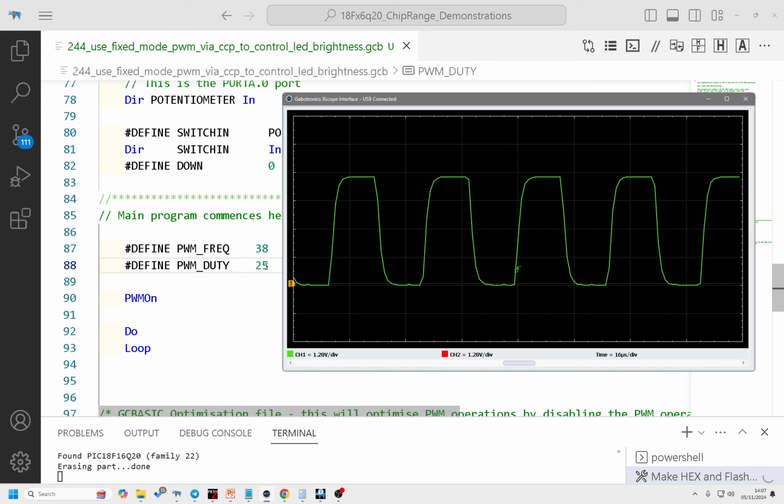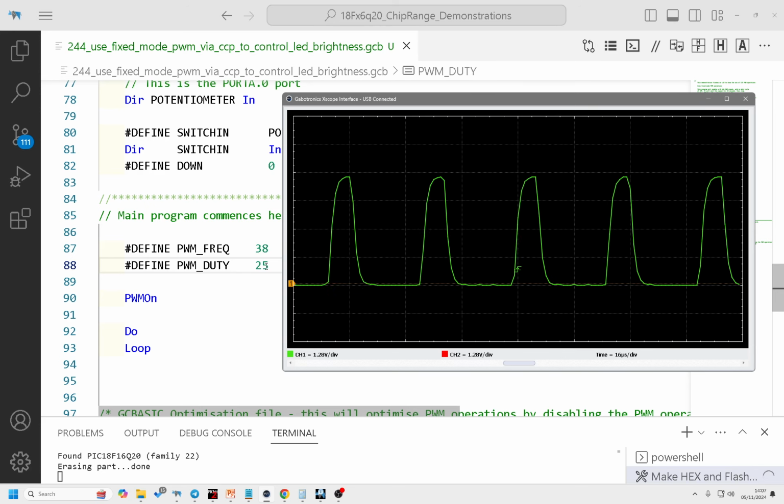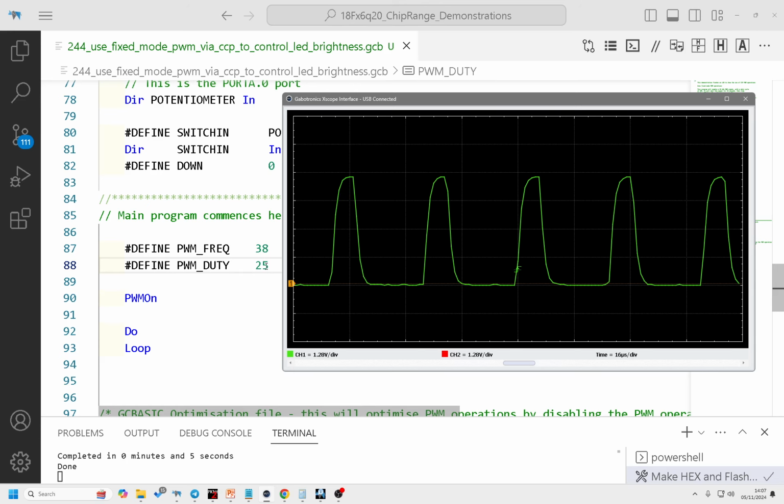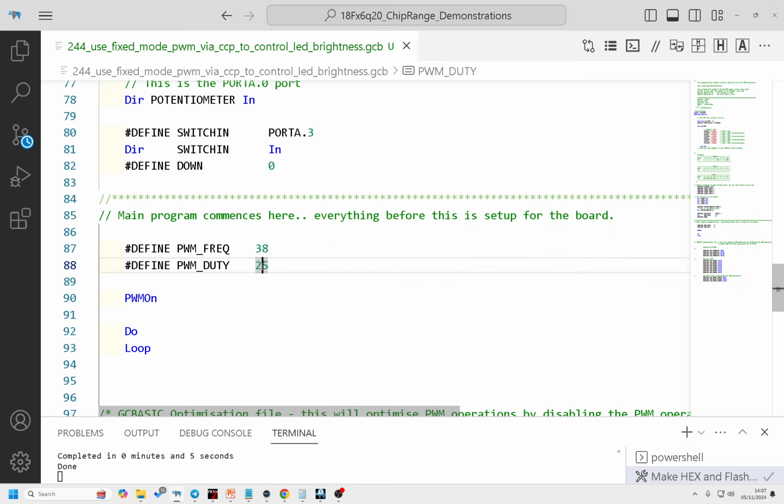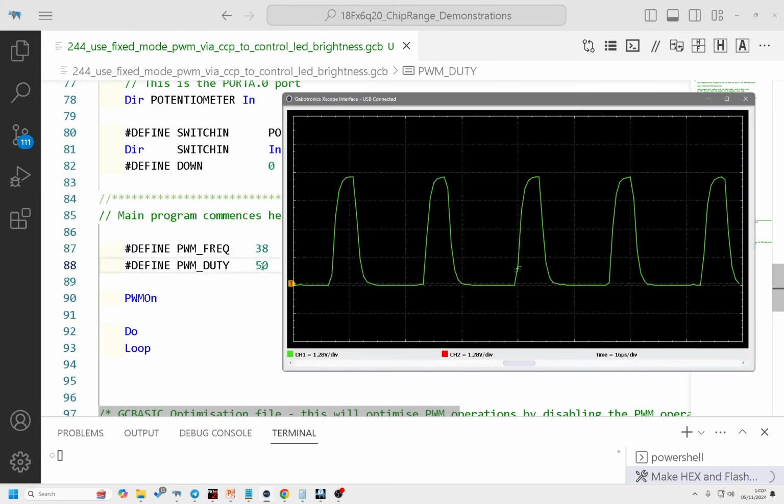But it's static. You can change it. You just have to dig into the code a bit. You can actually change the duty cycles and the frequencies, but you'll have to learn the registers. This needs no register knowledge. The whole point of this is there's no register knowledge. So I'm putting that back to 50% because this is pristine code.